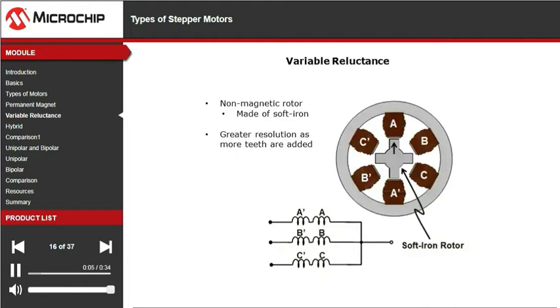This motor uses a non-magnetized, soft iron rotor that actually has teeth that are carefully offset from the stator poles to accomplish rotation. Notice also that the individual stator windings are configured differently than what has been discussed so far. All the windings have a common terminal that will be connected to a voltage source, while the opposite end of each winding is kept separate from the other windings.